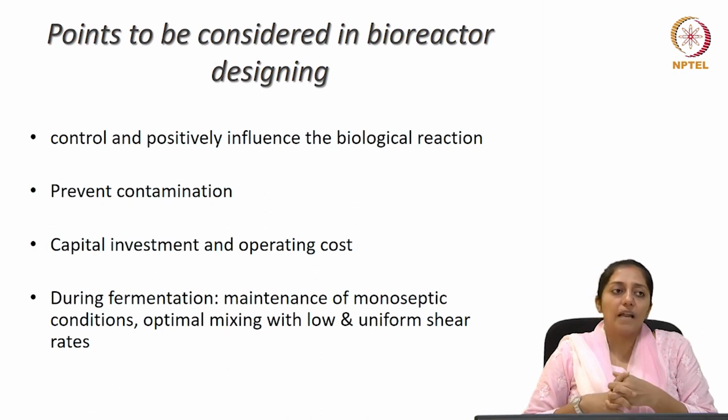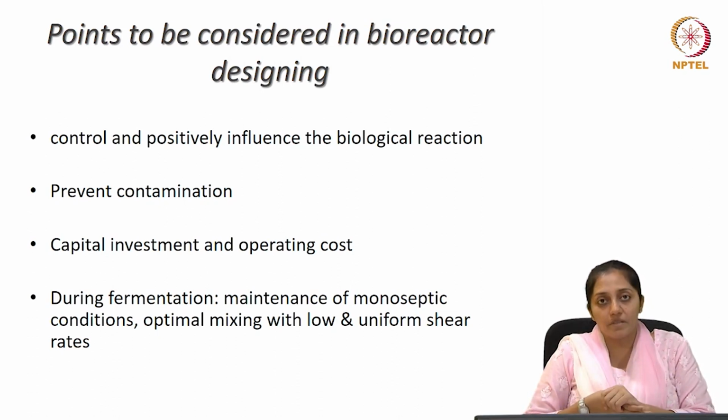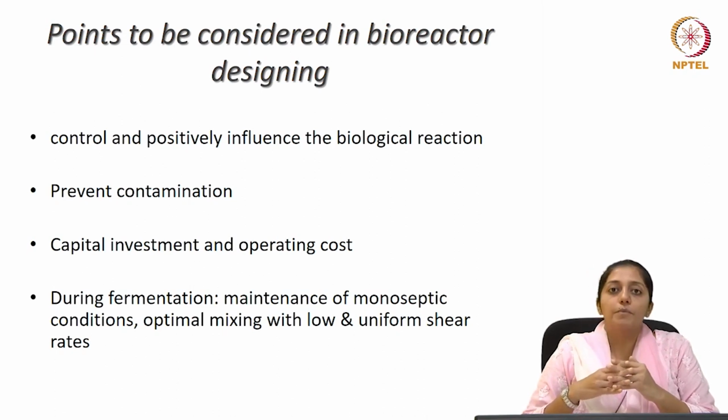Depending on the production platforms being used, the fermentation time can vary from hours to days and even sometimes to months. So the chosen reactor design should therefore also look into factors like optimal mixing, optimal heat transfer, and with low and uniform shear requirements for maximum viability of the culture to achieve maximum productivity.